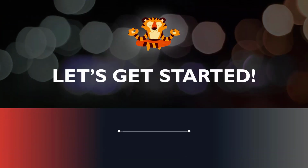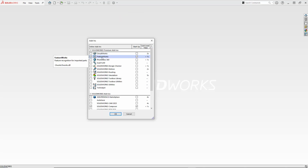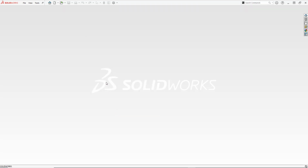So let's go ahead and get started. I've got SOLIDWORKS open here. First things first, let's make sure the FeatureWorks add-in is active. From the main menu bar up here, I'll go in the options drop-down and select Add-Ins and just ensure that FeatureWorks is checked. I have it checked to start up, so it'll happen every time I start SOLIDWORKS. Go ahead and click OK.